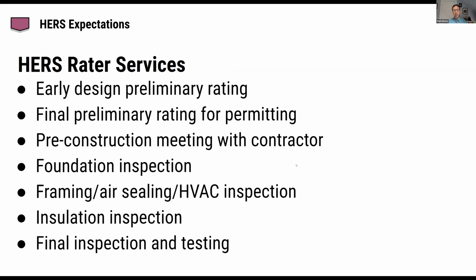And then pretty much any HERS rater needs to provide a final preliminary rating for you to pull a building permit. Some will provide a pre-construction meeting with your contractor to walk them through everything that they're going to be looking for. Some will provide a foundation inspection. Some will provide a framing or air sealing or HVAC and rough inspection during construction. And then every HERS rater will provide an installation inspection and a final inspection with testing.